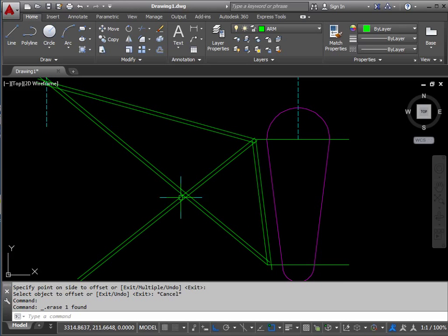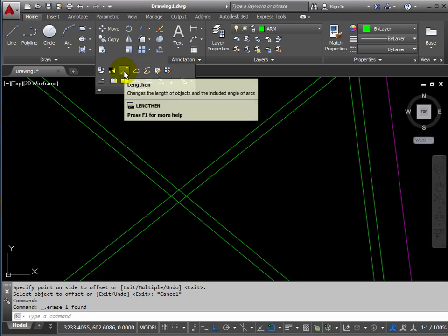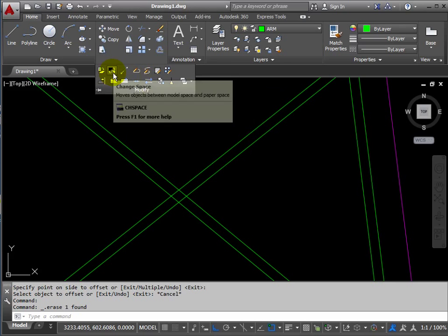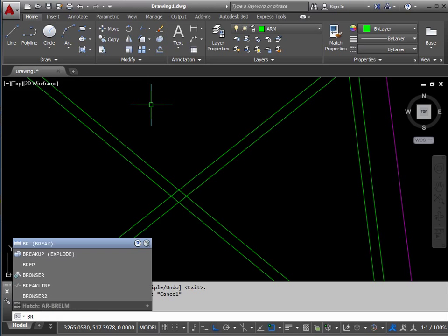The truss is really taking shape now, but as you can see these lines are much too long and untidy. What I need to do is to try and make a joint appear this side and a joint to go that side. Using fillet, I would lose one end of this line repeatedly. I would just get in a mess. What I need to do first is to break the line so I can tidy up one side and tidy up the other side. So let's get in a bit closer. The break command, I saw it on here. Where is it again? Join, break is somewhere around. I always lose them. So I'm just going to type it in. It shortens to BR for break.